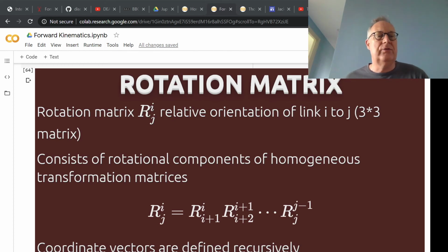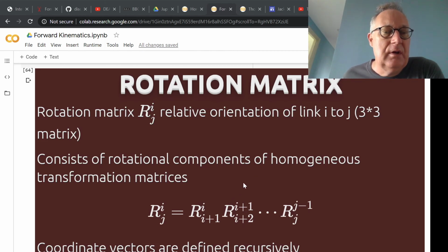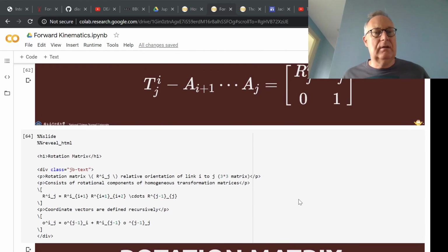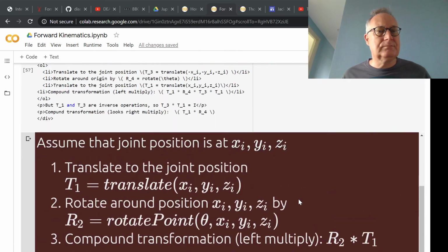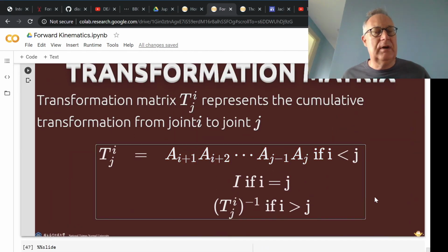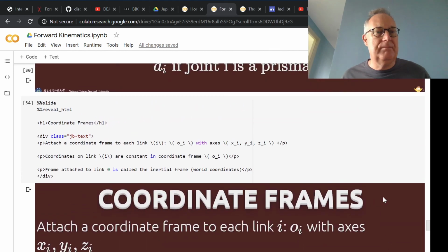In theory now I could solve it, right? If I have given joint coordinates theta 1, theta 2, theta 3, then I can calculate these rotation matrices and the transformations with the origins. Then I can calculate the end effector position. All that is required is to find this H matrix. However, that is possible, but it's not a very elegant, very smart way to go about it.